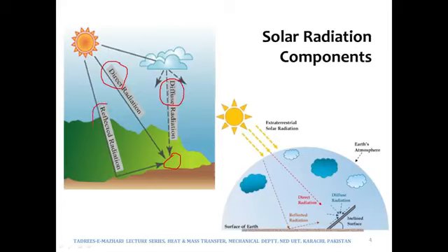And then there is a third type of radiation which is reflected off the ground. It did not hit this surface directly or indirectly. Rather, the radiation first hit the ground, and it was then reflected off the ground, and then it reached the surface. So if this is the surface, the radiation that it will receive would be the sum of direct, diffuse and reflected. Sometimes the reflected component is very small, and some people neglect it under certain circumstances. It would depend upon the reflectivity of the ground.